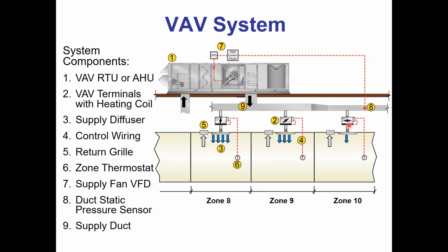The current codes no longer allow us to put it 2/3 down the duct. We'll explain later on at the end of today's presentation what the current codes make us do. But for right now, we'll go with the traditional scenario, which is putting it 2/3 down the duct.